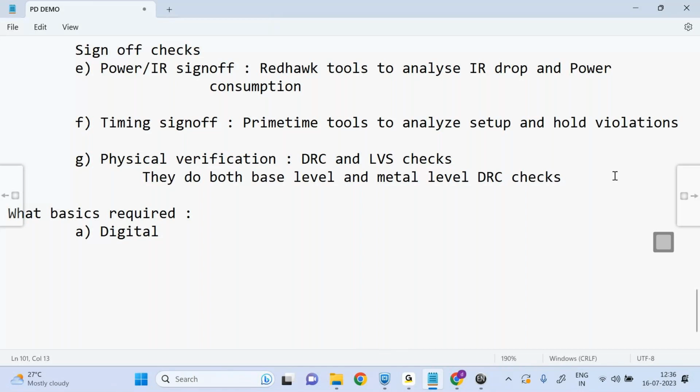So what is the meaning of asynchronous reset? Yes, to affect the value of reset, we don't want a clock edge. Alright. What is the difference between latch and flip flop? Latch is level triggered, flip flop is edge triggered. So like that, you should know the digital properly. Then only we can do static timing analysis properly, or else it is very difficult to do.